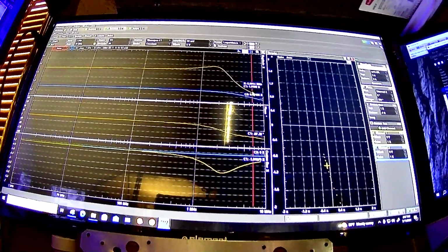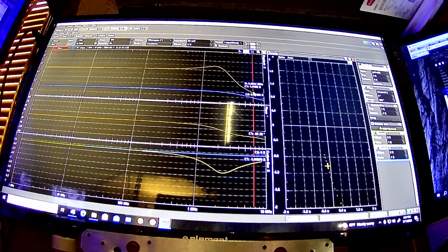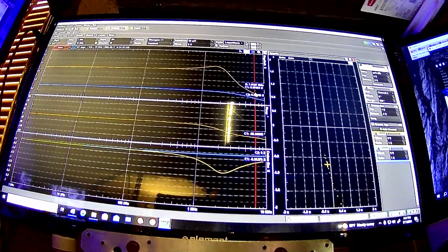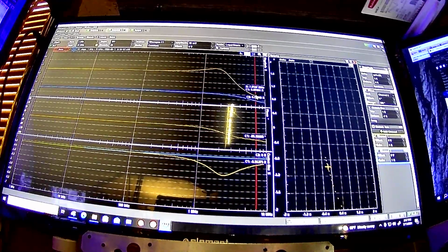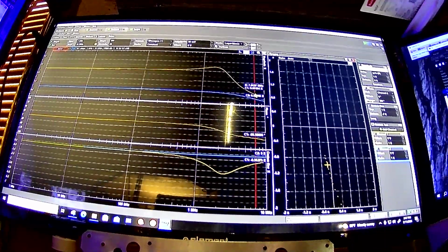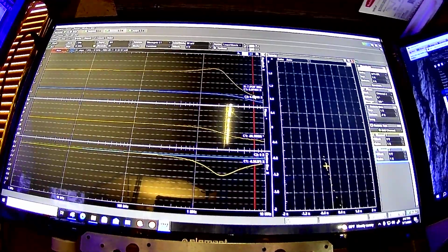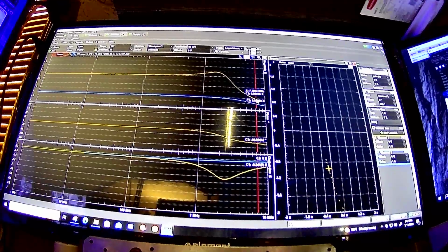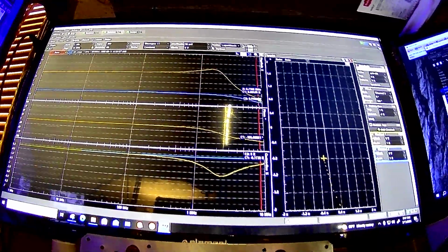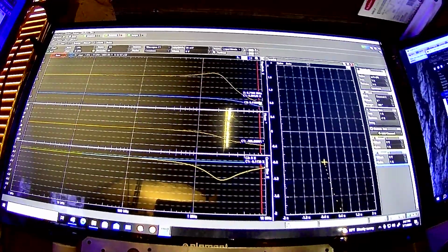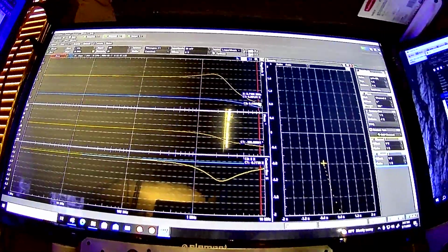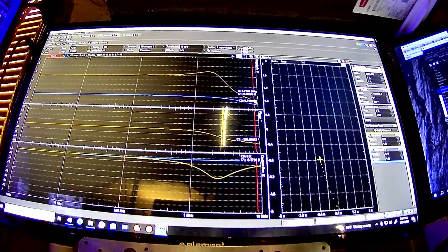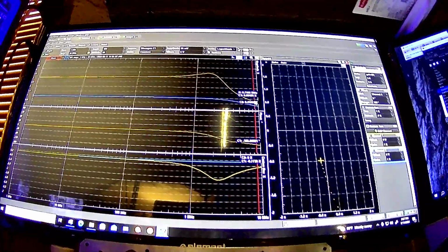Because again, it should be unity gain out to 1 megahertz, and sometimes you can still get that even with gain feedback on your op amp. At least I've noticed it appeared that way on some. Even if you set your gain to like 10, you still might actually have unity gain out to some frequency, but it's special with a non-inverting amplifier because generally you can't set your gain to be less than 1, and that's one of the reasons.